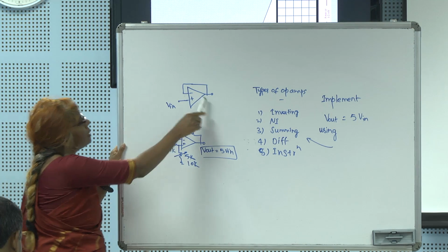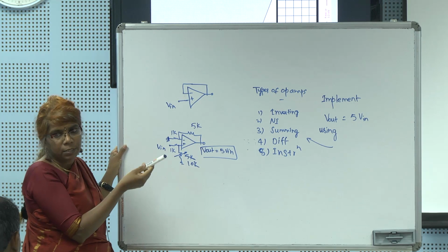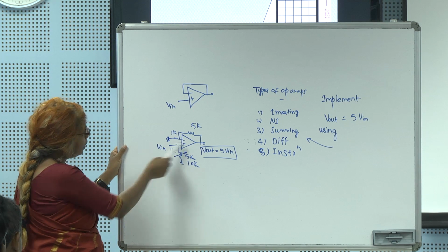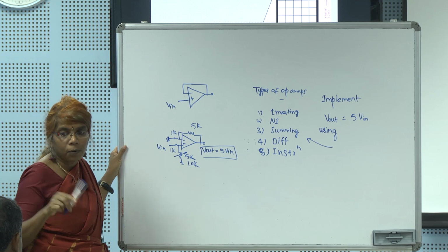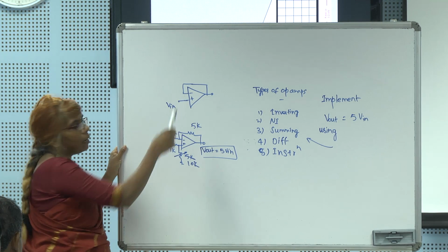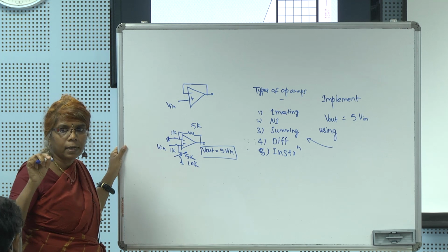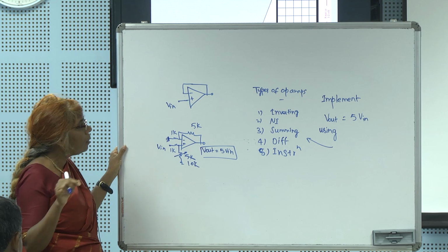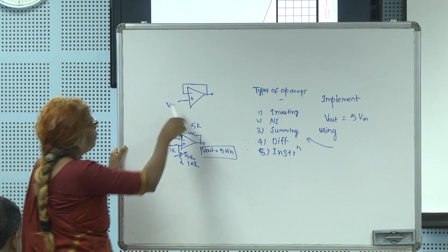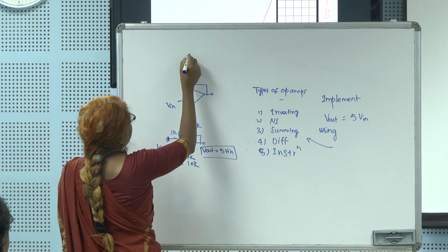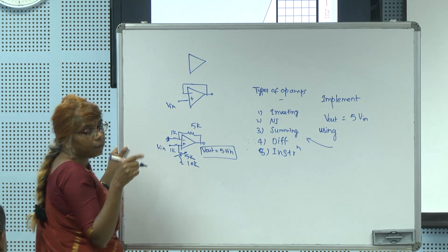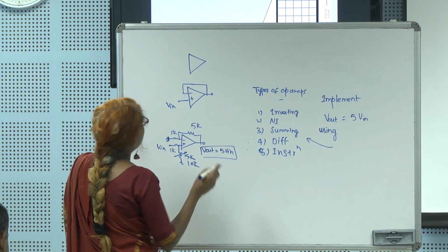So, why do we use this? For instrumentation, that is the difference, correct. We cannot take directly here because of the low input impedance. Because the op-amps are noted for very high input impedance, low output impedance, we will have this voltage follower. This is how we do that instrumentation op-amp. This is what we are going to do for our ECG, EMG, EEG, all that.